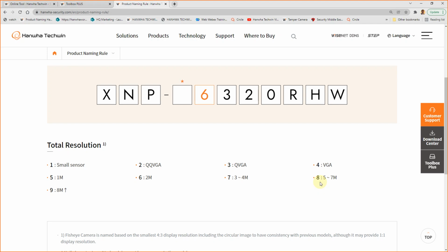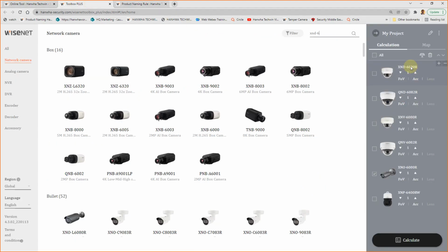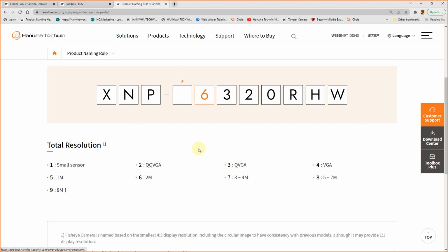He's not going to make it complicated for himself. The first thing a consultant will decide is what should be the resolution for all the cameras in my project. So it will be fixed. So in case in your BOQ you find all six, but one of them is maybe less than six, that means something is wrong. You should take note and investigate why one of the cameras is lesser. Who accepted it? Will the project accept a lower resolution? All right, this is something you have to keep in mind.